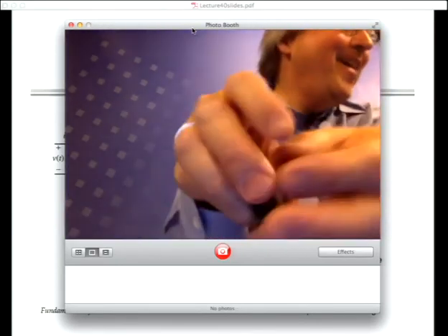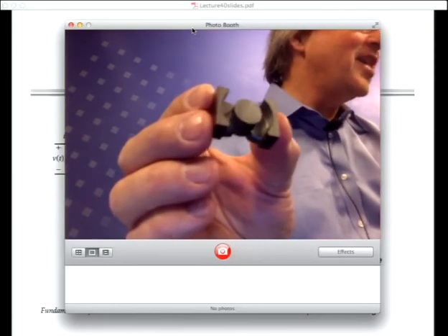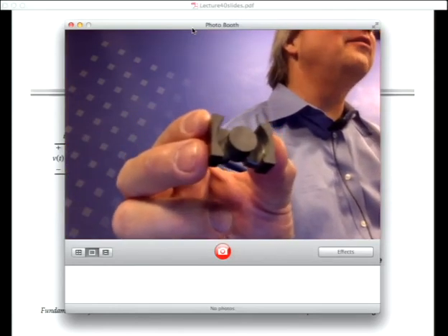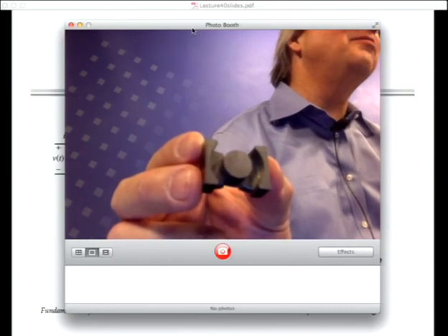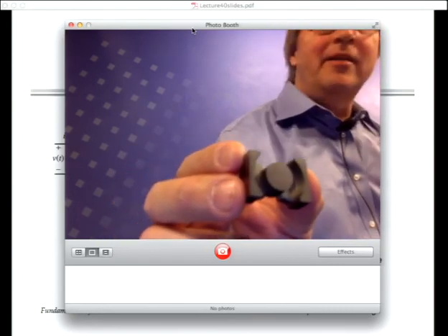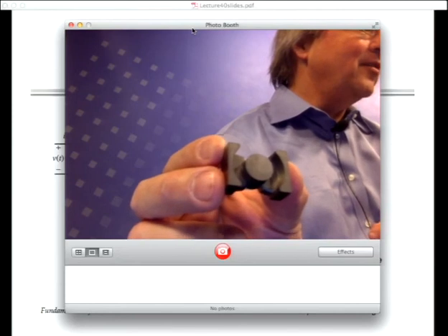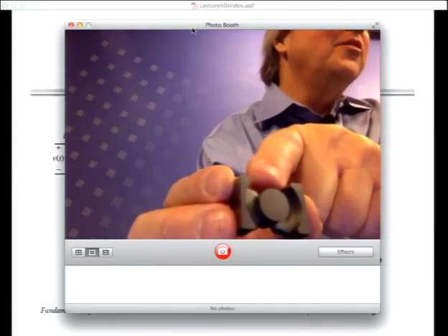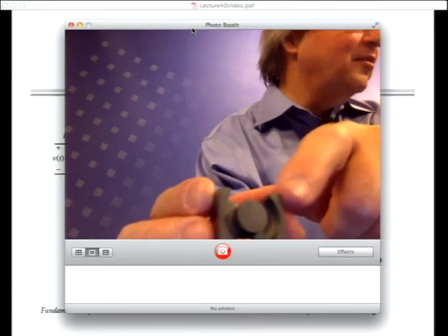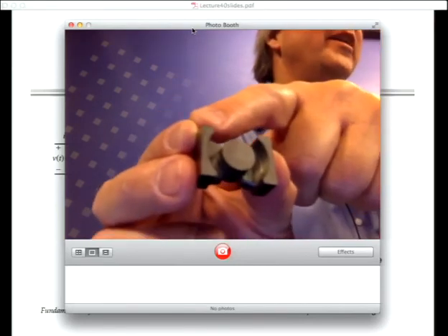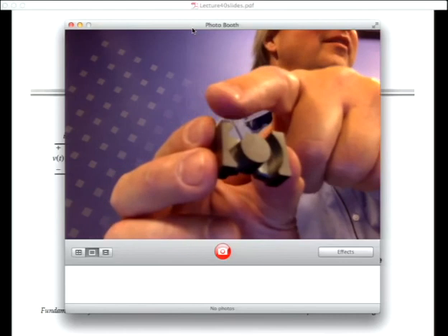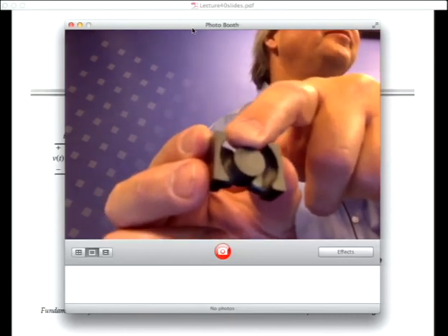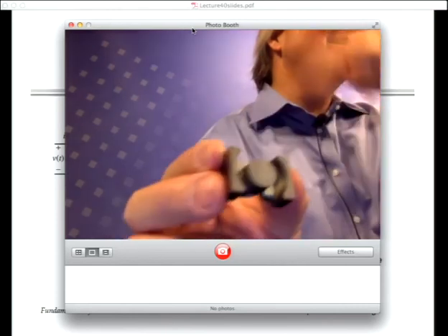Yeah, so let's see, there's the shape. The round center post has an area that you could say is AC, the area of the core, but it's round instead of square. What happens actually is that of the flux that goes in the center post, as it goes around the magnetic path, half of it goes on one leg and half goes on the other leg. And if they design this right, the areas of the two outer legs should add up to the area of the center post. So it's a wash. So then it's constant area going all the way around.